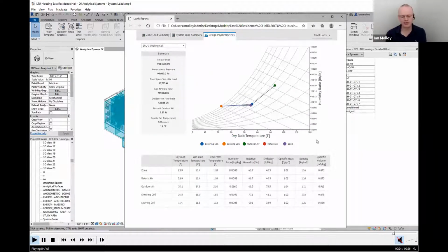This is a new feature that's now in Revit 2022. It's brand new, out only a couple of weeks ago. This is all built using EnergyPlus and OpenStudio. The reports work in both metric and IP units. They're supported in all the languages that Revit works with, but critically, it's all entirely customizable. You don't have to be tied into the way this report works. If you wanted to add another column in here for any reason, you can use the OpenStudio results measures to add those in and customize the report a little bit more.